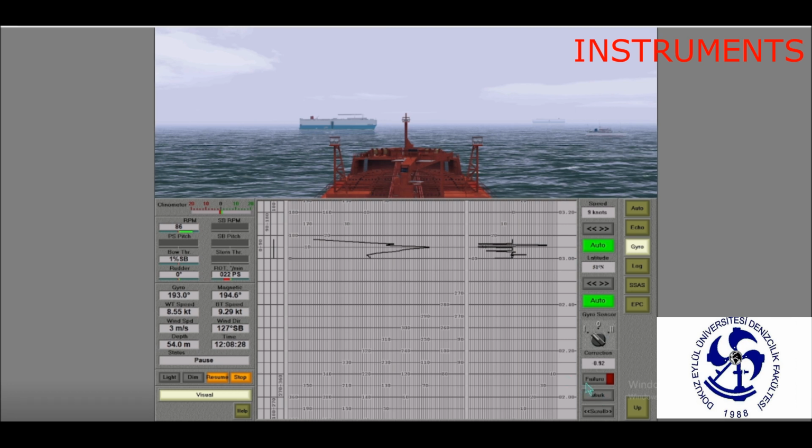The automatic calculations of the gyro velocity correction require the vessel speed and the vessel's position latitude. To this end, the speed, latitude windows and double arrow buttons are used. If a log and GPS receiver are used, the required values will be entered automatically, as demonstrated by the lighted green auto buttons.